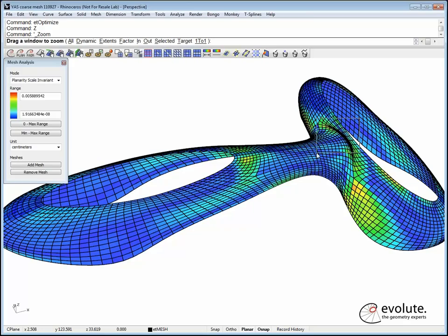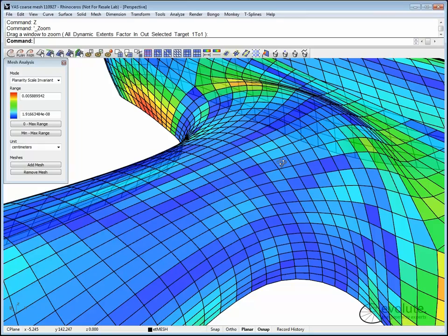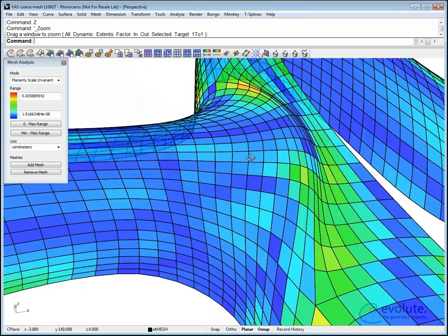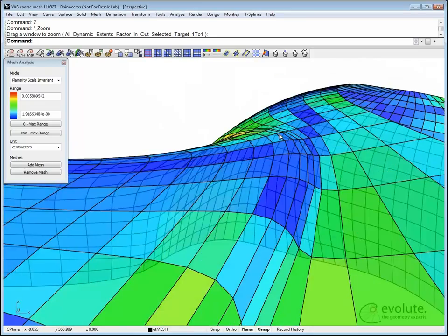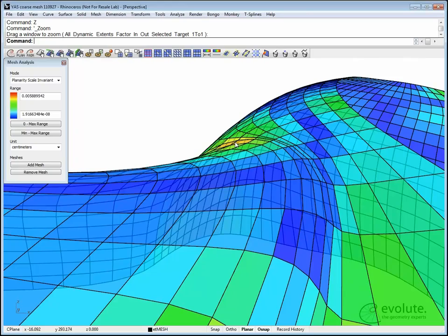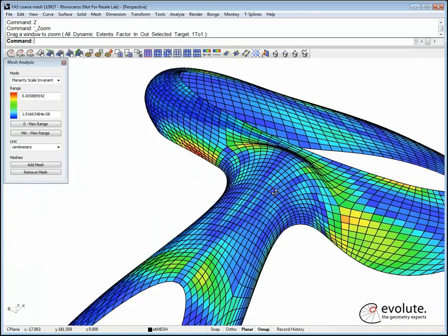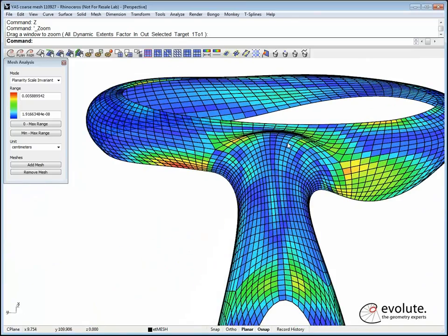Of course, there are downsides, no doubt about it. You can see that the power of the optimization algorithm is desperately trying to move these vertices on your reference surface in order to get all those quads flat. So this is basically when you have some bunching up of your panel layout in some areas.